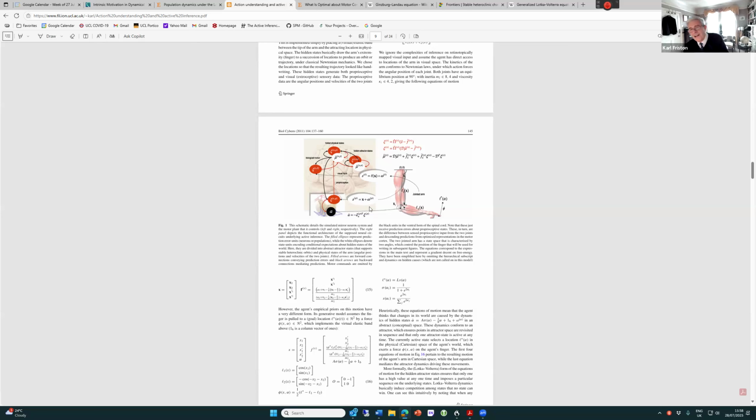I'll try and explain why it's simple, because all you need to do is to give the generative model these priors, these dynamics, and then it creates predictions in both the visual domain, if you have an RGB feed, and the proprioceptive or pose domains, which are the kind of things that you get from feedback from your motor plant or from your robotic arm.